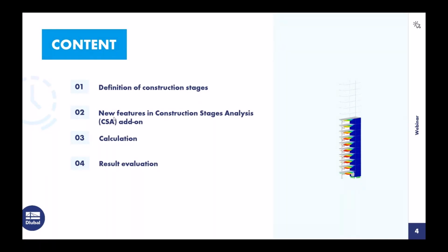I will show three different examples. One quite simple example in the beginning to show some basic principles of the construction stages analysis in combination with the time-dependent analysis, especially regarding long-term deflection or long-term behavior regarding creeping.